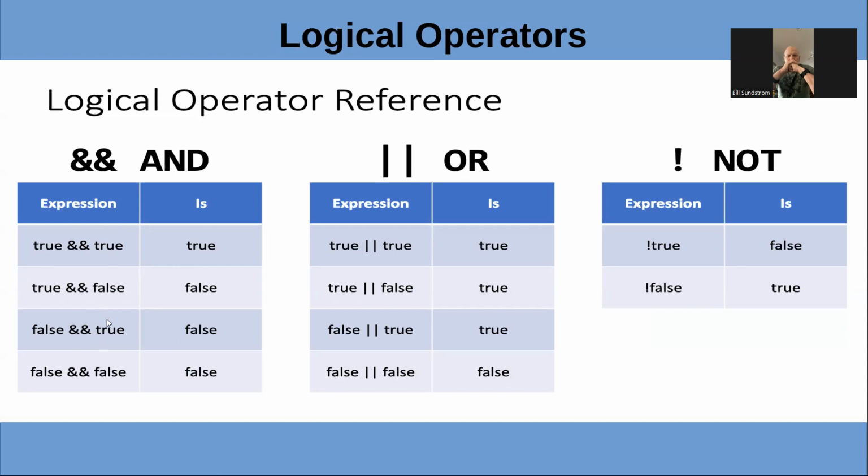If I have a false and a true, the output will be false. If I have a false and a false, the output will be false. So for an AND gate, the only time the output is true is when all of the inputs are true. It doesn't have to be just two, it can be 3 or 4, or however many. I think I've seen maybe up to 8 in a single package.